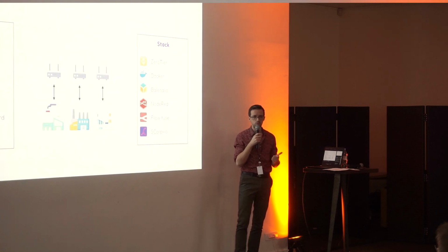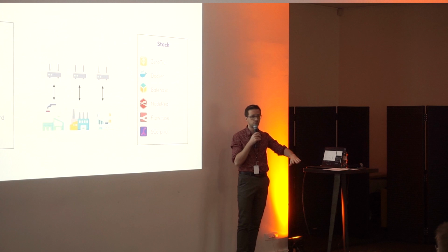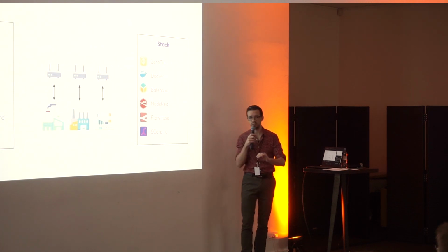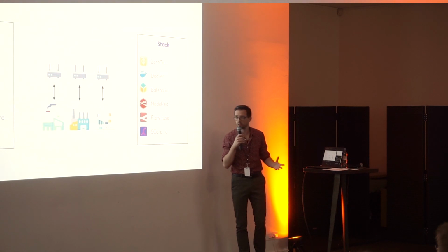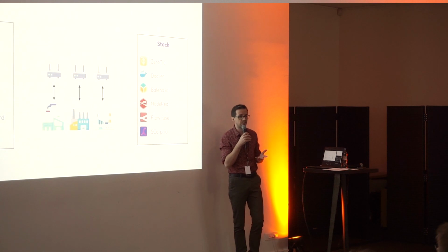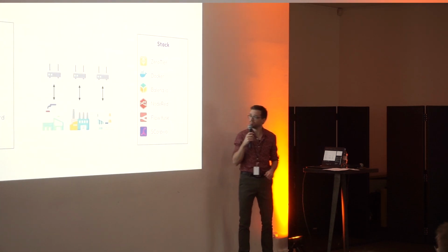Believe me, you don't want useless data on the cloud. To get rid of useless data, you have to fix sampling and hysteresis the best way possible. Otherwise, you're going to be flooded with useless data, and useless data is a mess at the end.